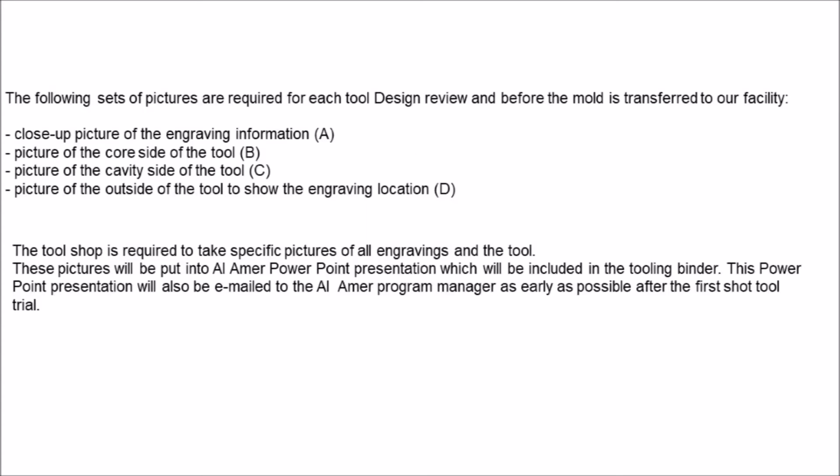The following sets of pictures are required for each tool design review and before the mold is transferred to our facility. Close-up picture of the engraving information. Picture of the core side of the tool. Picture of the cavity side of the tool. Picture of the outside of the tool to show the engraving location.